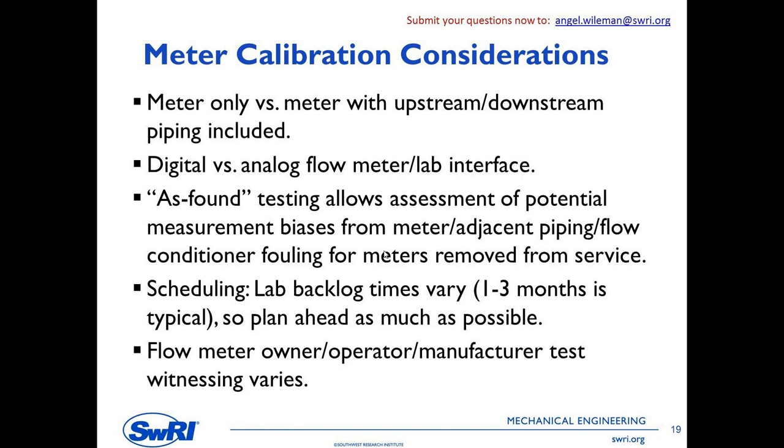If you can tell, I'm a little biased, you shouldn't do that unless you want not as accurate flow. But the other type of quasi-analog output would be a pulse. So a pulse train is a very good way of doing output from most modern meters, and turbine meters all have that type of capability. And so then the lab has to interface to those devices as well.